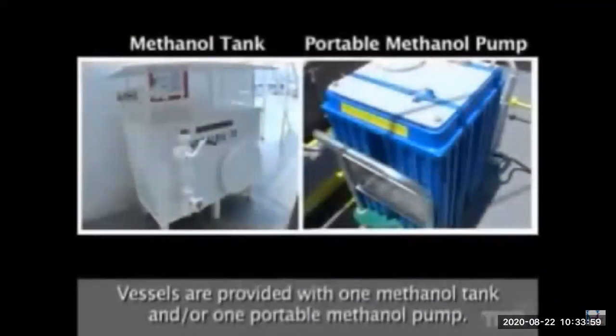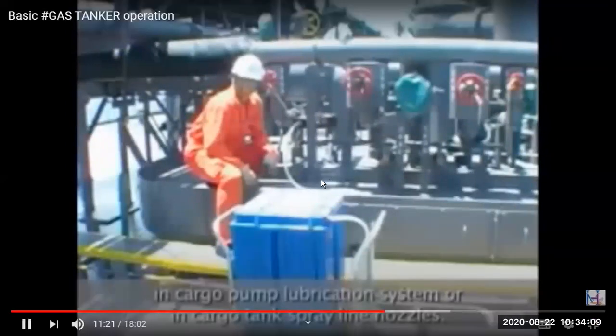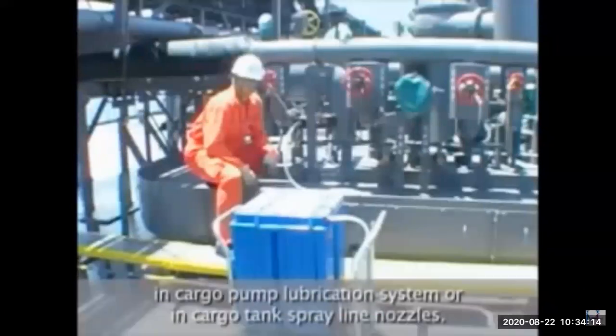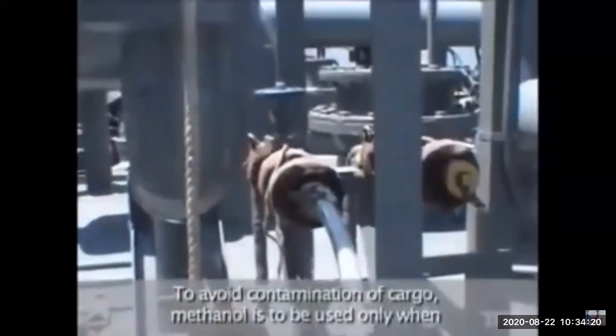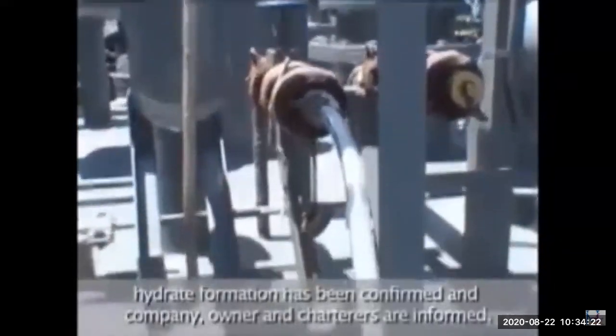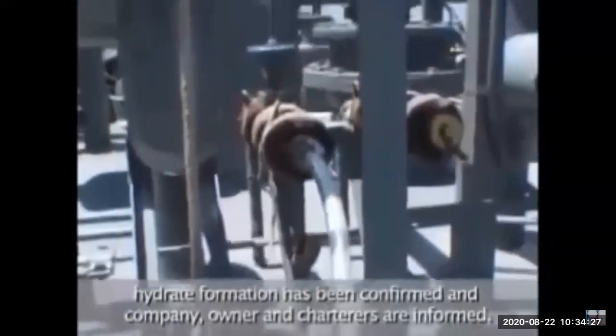The methanol tanks, one or more portable methanol pumps are there, which are used as anti-freezer on LPG vessels to remove the hydrate formation. As we told, we are loading gases at very low minus temperatures, and this water moisture, if it gets crystallized, can form hydrates. The crystals of water can damage the pump while discharging. So to avoid that, we can put methanol, but we have to take permission from the charterer.